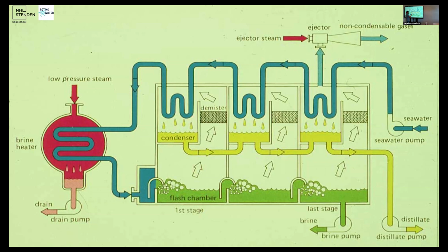So as I said, this evaporation happens at a very specific pressure. The moment you start to evaporate in a flash chamber, you will condense some vapor, but of course there will be non-condensable gases. If you don't exhaust these non-condensable gases, you can build up pressure inside your chamber, and then you move in the phase diagram to another position, which will decrease your flashing chamber efficiency, but could also at the end compromise your condenser efficiency.